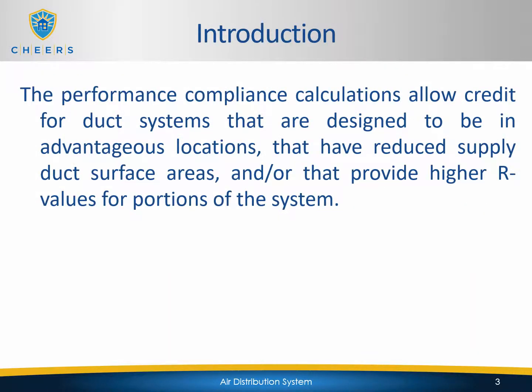The performance compliance calculations allow credit for duct systems that are designed to be in advantageous locations, that have reduced supplied duct surface areas, and/or that provide higher R values for portions of the system.